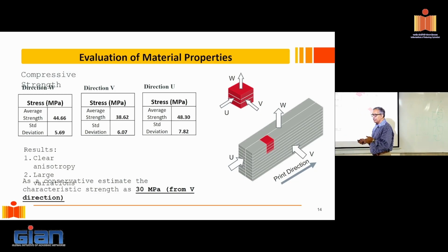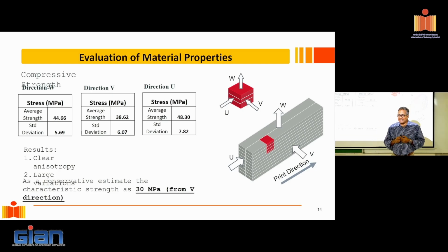This is the standard deviation. 1.65 times this happens to be conveniently around 30 megapascal. Okay, so for this concrete, can I pretend as if it is 30 megapascal concrete in all directions? Seems like a good way of thinking, isn't it?